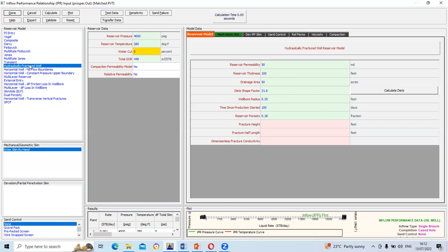And one of the ways to solve that problem is to carry out what we call hydraulic fracturing. You send in fluid that is mixed with proppant. This proppant could be sand grain. You inject it at high pressure within the reservoir, and then it creates highly conductive pathways through which fluid can easily flow. That's hydraulic fracturing. I think it's part of our internship, for week 10, we have to look at hydraulic fracturing simulation using FracPro.